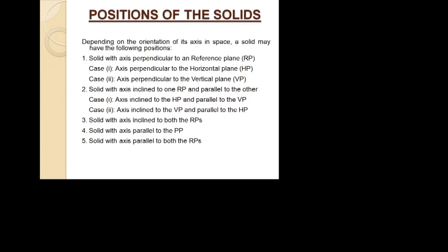In the first stage, the axis is perpendicular to HP. It is clearly mentioned. So first we have to draw the axis perpendicularly below the reference plane, and above the reference plane you can see the triangle shape. This above face has to be tilted in the condition that it is freely suspended.